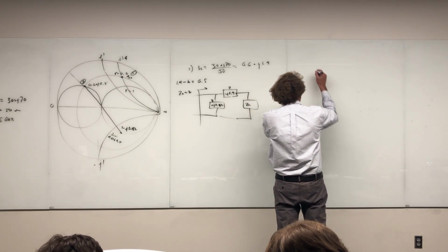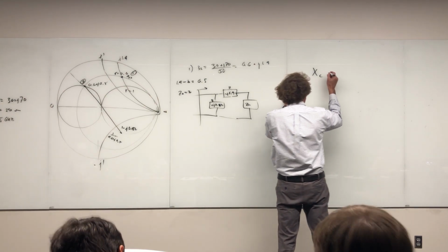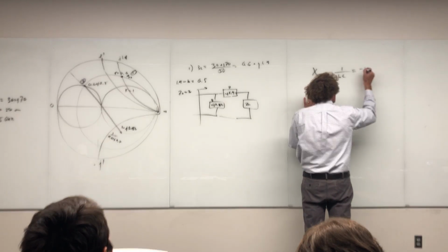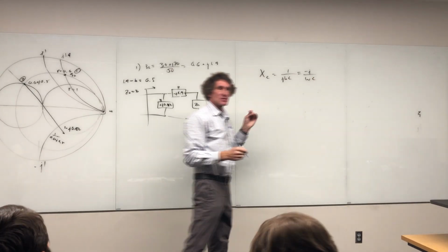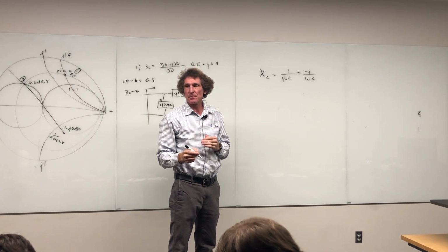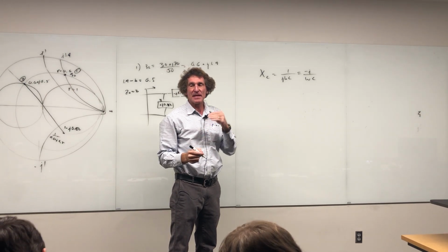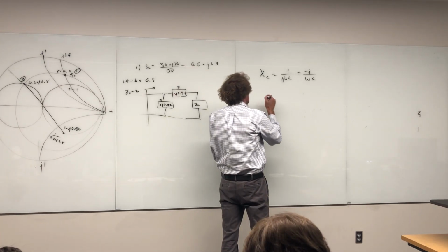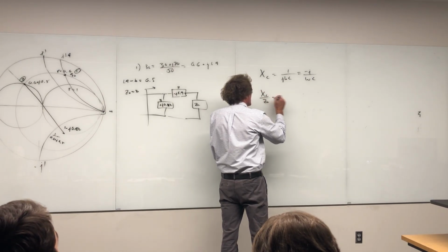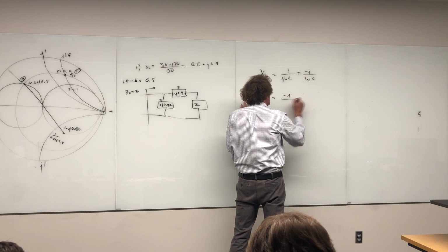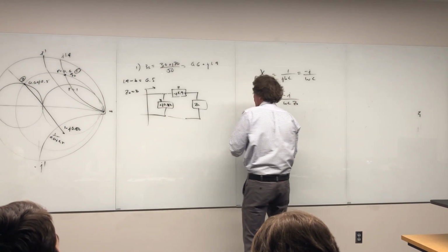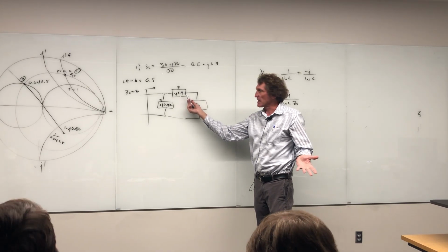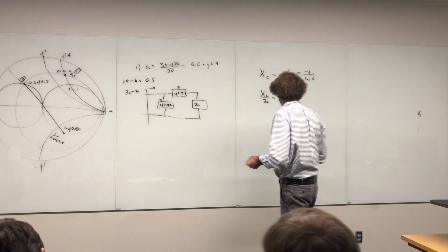That's a capacitor. We know capacitive reactance or impedance is simply 1 over J omega C, or minus J over omega C. I'm going to go slow one more time on this just to really underscore this. Now, if I have that, the next thing I have to do is normalize it. Second step is normalization. So then I get X sub C over Z naught, and that's going to be minus J over omega C Z naught. We're putting an impedance. We don't do 1 over here, right? It's an impedance. That impedance has got to be equal to minus J0.9.